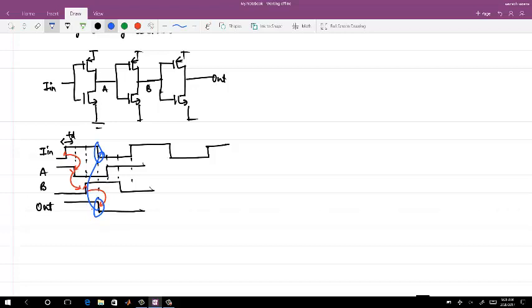That means if T was the period at which I was trying to trigger my delay chain, if T by 2 equals 3 times the TD delay, then I can close the loop.